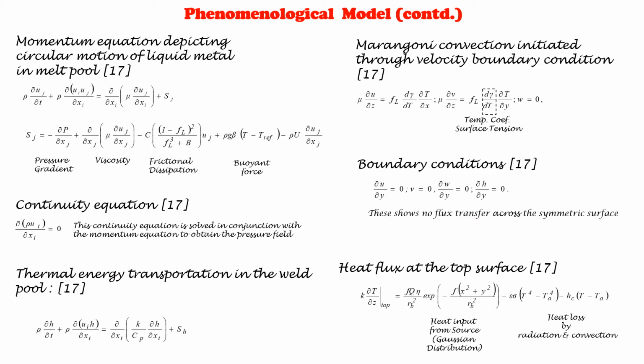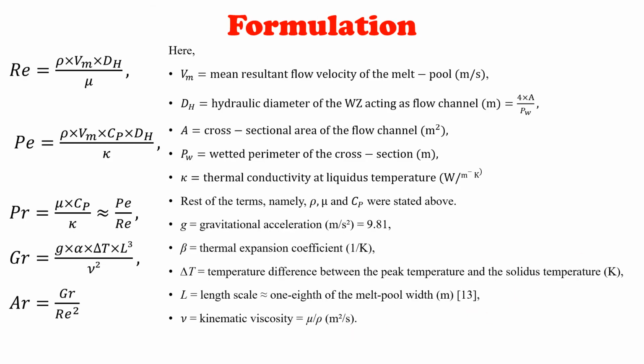Now, the equations utilized in the CFD-based phenomenological model include momentum equation, continuity equation, then transportation equation, Marangoni convection forces, boundary condition, and finally heat flux which is acting at the top of the surface.